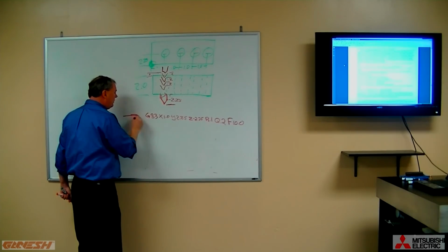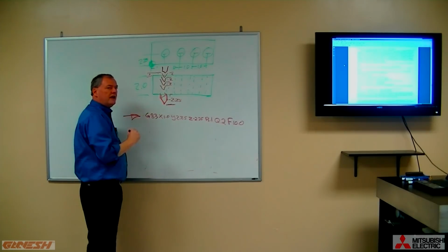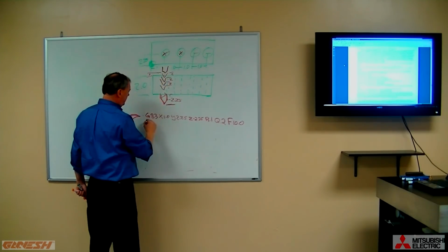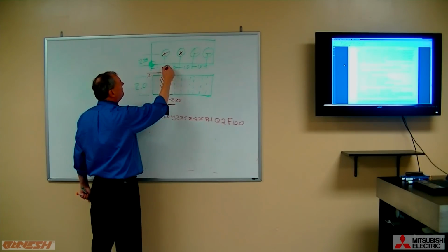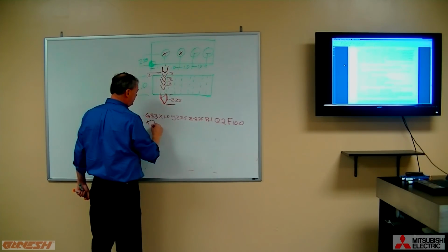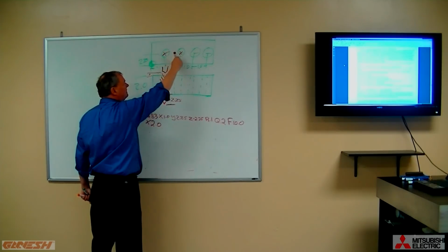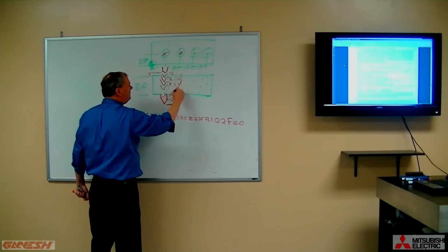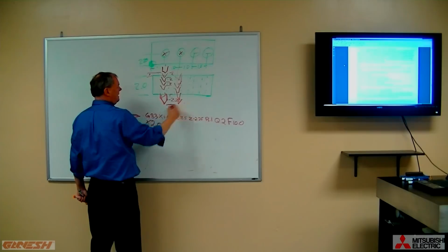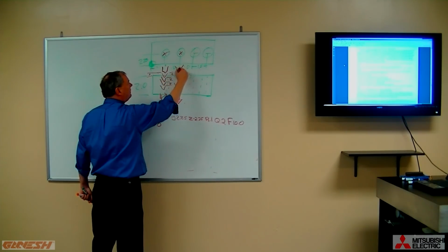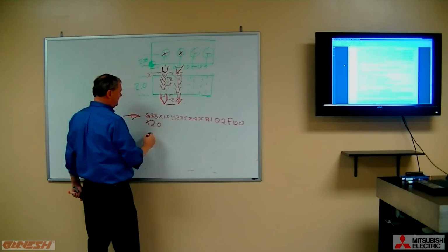This is the first hole occurrence, and because we turned on the G83, all we need to do now is give it the next location, X, so that would be 2 inches, right? The original one plus another one, so that's X 2.0. And now it's going to do the same thing right here until it reaches its depth. And it'll be sitting right here, ready for another command, and now we tell it X 3.0.